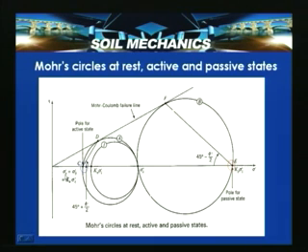So, sigma x dash is equal to sigma 3 dash, the minor principal stress, which is Ka times sigma z dash, that is, the coefficient of active earth pressure times sigma z dash. If you compare water and soil, they have some resemblance. Like water, soil exerts lateral earth pressure, as we discussed in the previous lecture. Here Ka is the coefficient of earth pressure in the active state.